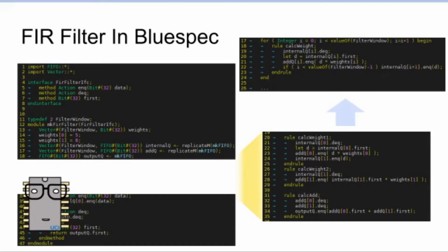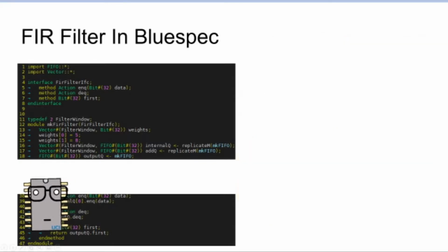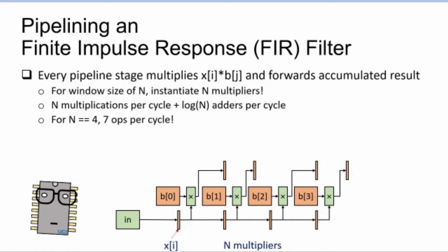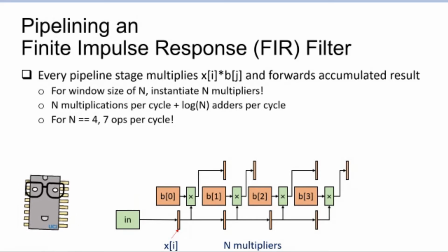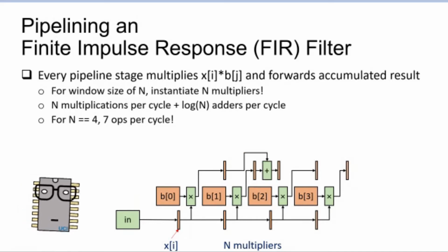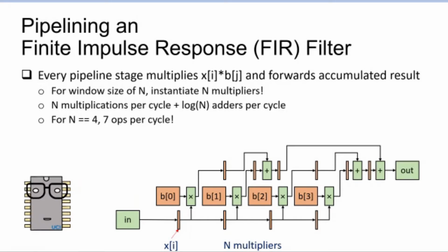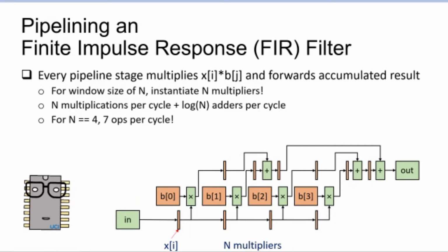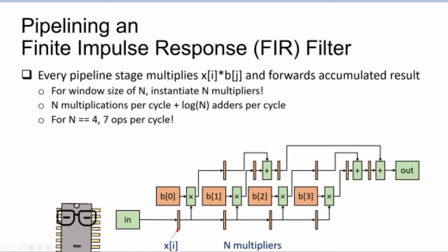So our design was to have, and this is going to be typical, this is the typical theme for all the designs that we do for FPGAs, is to have multiple multipliers and a tree of adders, so that we can have all these arithmetic units operating in parallel, implemented in the form of a systolic array, so that data comes in without any blocking.